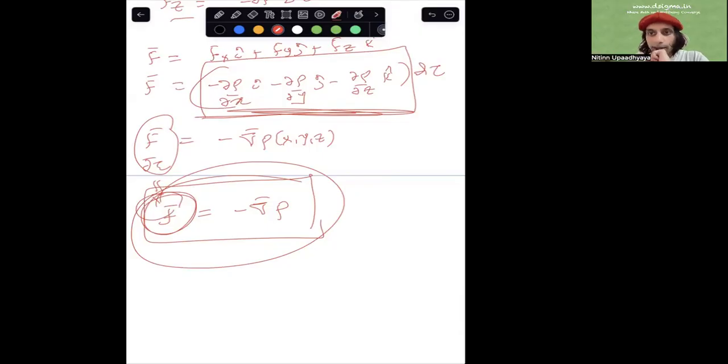Now, also remember that we had this discussion during the course on the introduction to differential calculus that normal to this direction, right? There is a direction where the pressure doesn't change at all. And maybe again, I refer you to the course, and these are sort of contour lines. So for a glass of water, these contour lines are orthogonal to the direction of the gradient vector. And this orthogonal direction is nothing but the horizontal slices or horizontal planes in that glass of water, right? So along a horizontal slice of the glass of water, the pressure doesn't change at all. Whereas as you move vertically up and down because of gravity, you will observe changes in pressure.